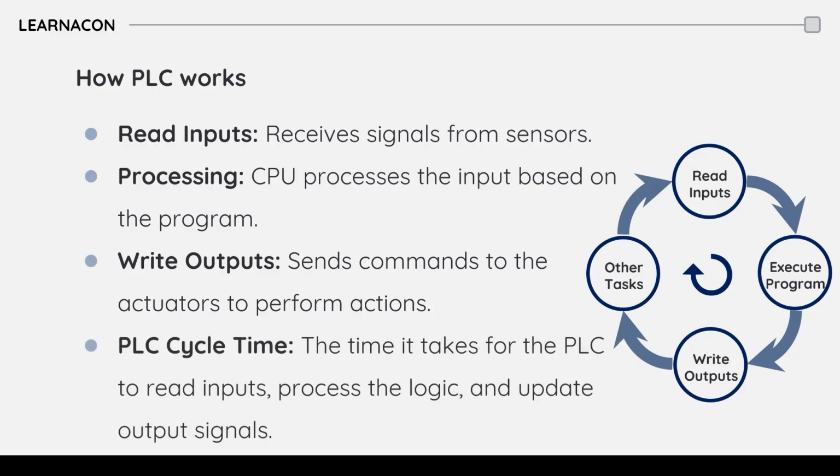The whole process of reading inputs, processing the logic, and updating the outputs happens in a cycle. The PLC cycle time is how long it takes to complete one full cycle. The faster the cycle time, the quicker the PLC can respond to the changes.